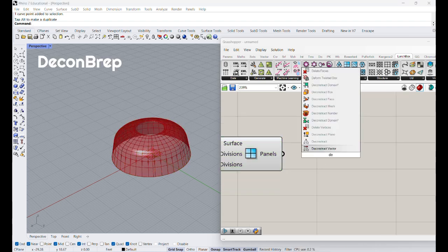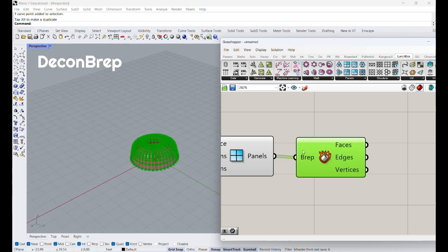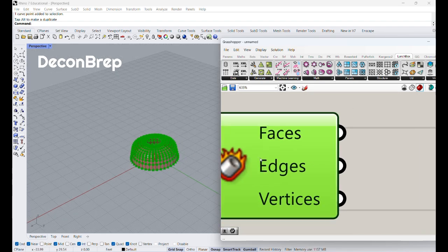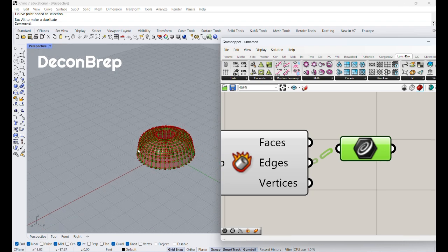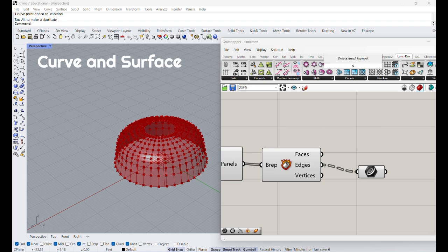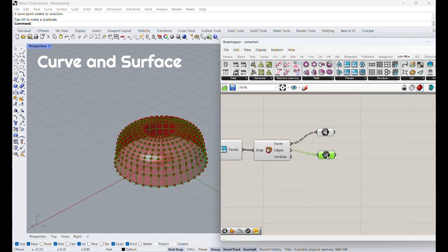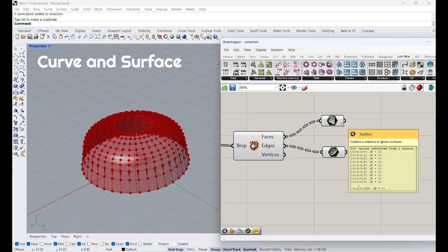In order to do that, I'm first going to decompose all of this, dividing it into, first of all, curves. The edges are curves. You see that this is all curves, all segmented straight lines. And then the surfaces. So those two are ready. In order to make all the geometry work in SAP2000, all the lines should be straight lines and the surfaces should be plane surfaces.